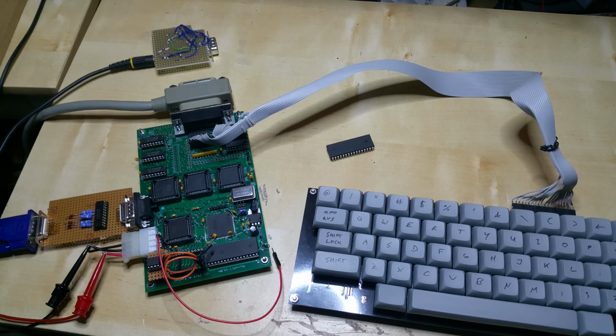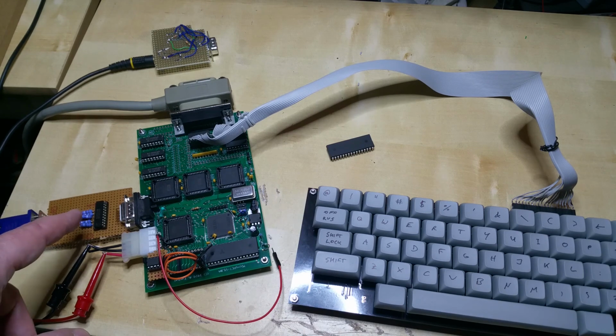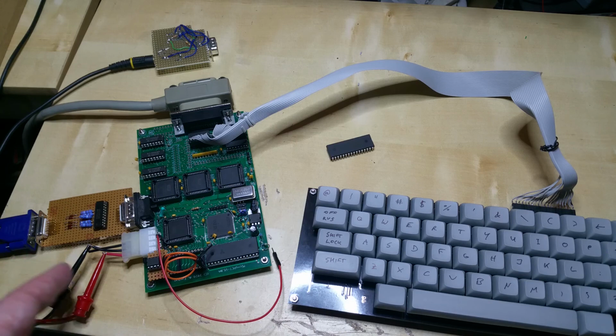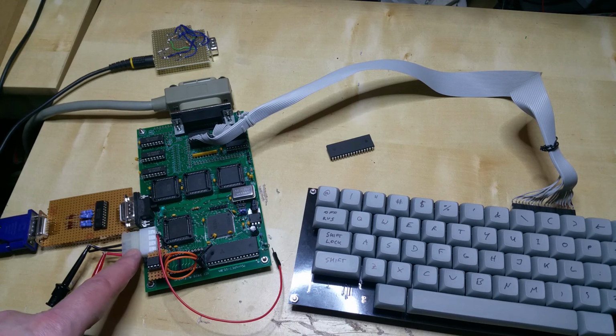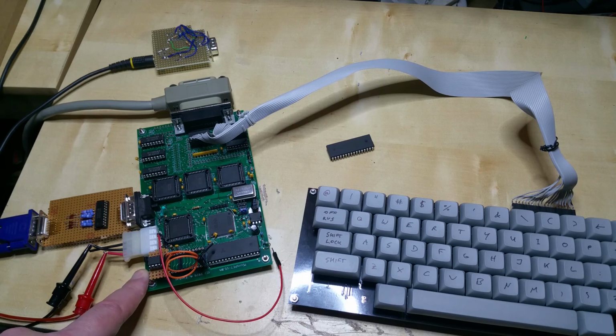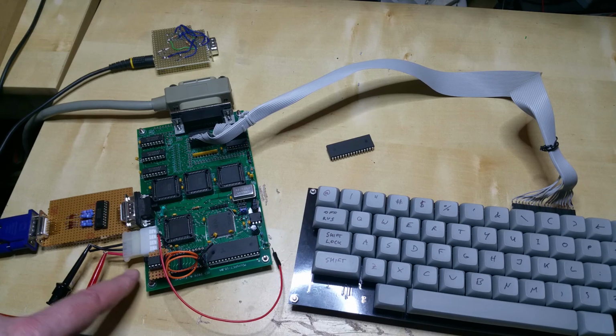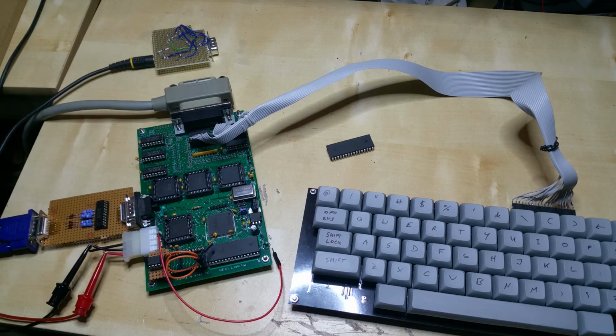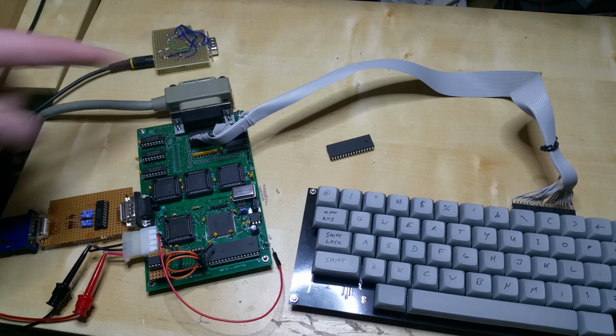Board 2 of the MicroPET will have some significant changes, but it's still an evolution. So it will have the VGA adapter included, with a connector for other adapters like composite or even HDMI. It will have a smaller power connector. I'm thinking about using micro USB or maybe something else. And then I'm planning on putting in board edge connectors, so you can use this board with your favorite extensions for the user port or cassette port, or especially the IEEE 488 cable, which is prohibitively expensive.